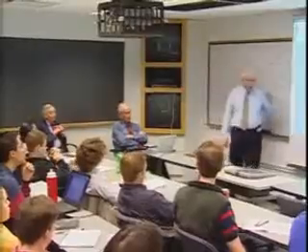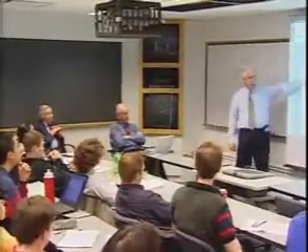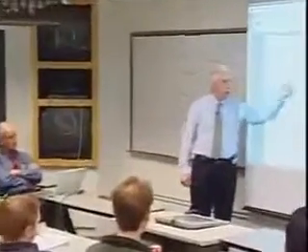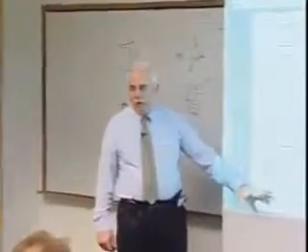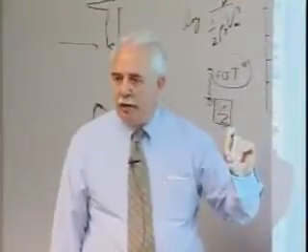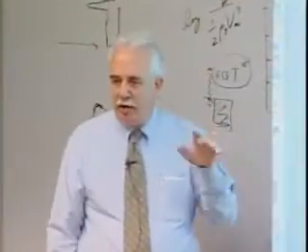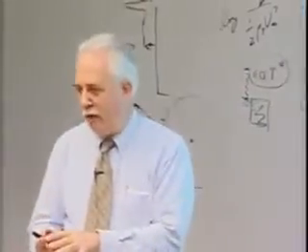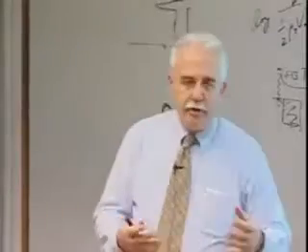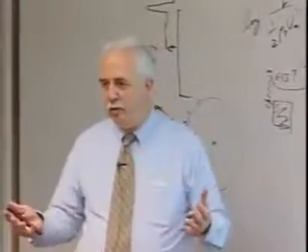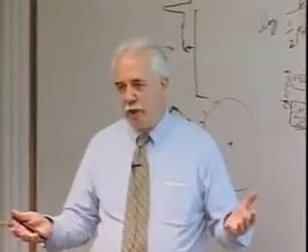Right. And I won't spend much time other than to say we first looked at smooth body transition. This is heating rate versus distance. Smooth body. And then we put roughnesses in. We actually went to cryogenic models with simulated tiles to get that boundary layer to suck down to be a little better simulation of flight. The alternative was to put bowling balls on the surface of the thing to try to trip the flow, and that didn't have anything to do with physical reality.